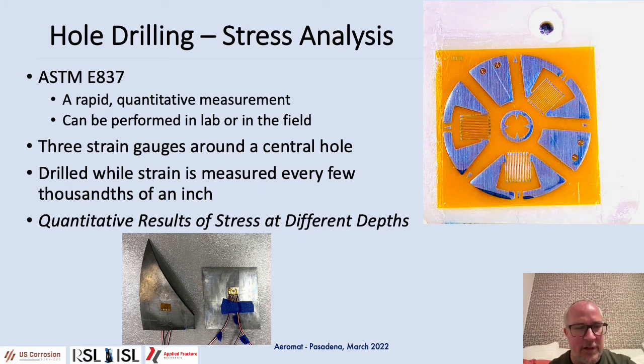And on the bottom left side, I'm showing some examples. The strain gauges can be applied onto curved materials, onto flat materials, and they come in a number of sizes and shapes, so they can be used in a lot of different applications where normally it would be difficult to measure stress, and where other techniques like neutron diffraction or X-ray diffraction would be difficult to apply. Also, another advantage is this is a semi-destructive technique. It does leave a small hole in the part, but especially for thick components, the hole can be ground out and it can still be used or further evaluated.